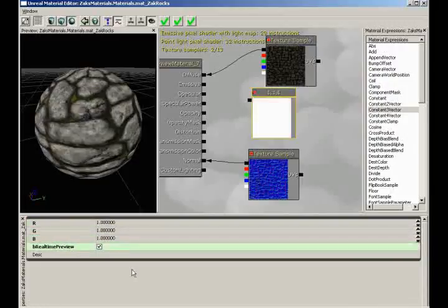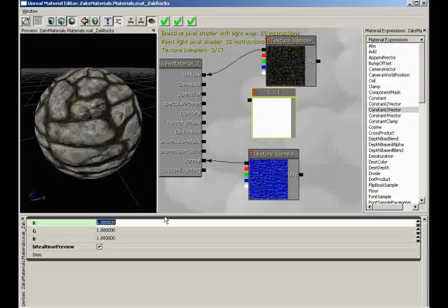By the way, just a tip, in case you've forgotten, this is true among many of the windows inside of Unreal Engine, a lot of the property windows. Don't use tab to jump from one field to the next. Use the down arrow key. Tab doesn't work. So we set all these to 1, so we have a value of white.